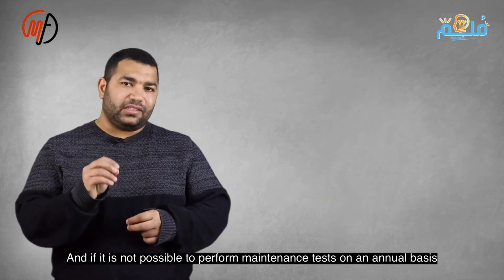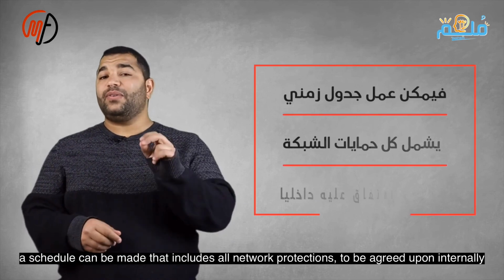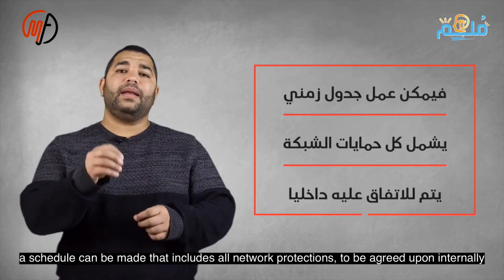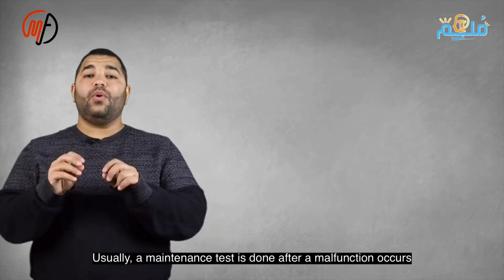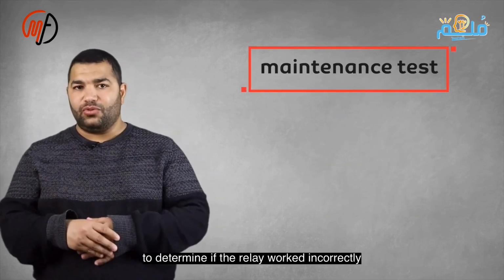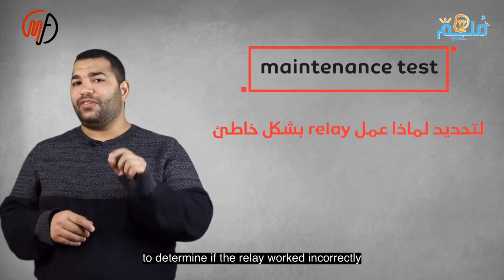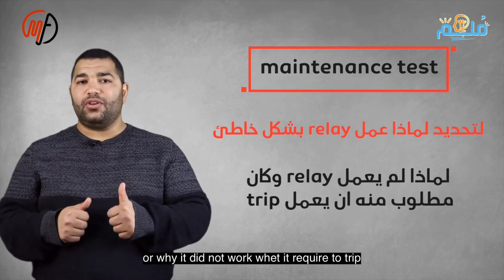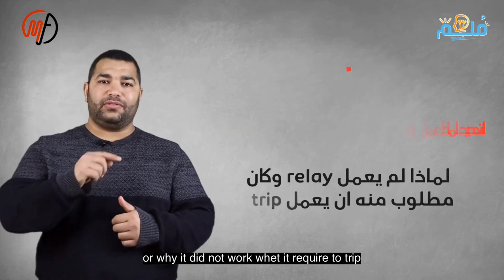Typically, tests are conducted after any malfunction to determine why the relay operated incorrectly or why it failed to operate when needed. Thus, we can simulate the same actual fault that occurred by pulling the voltage recorder from the relay in CFG format and placing it into modern testing software to recreate the fault. We can monitor the relay's response to the same fault again and identify the reasons for this malfunction. This process is also known as troubleshooting or post-fault investigation.